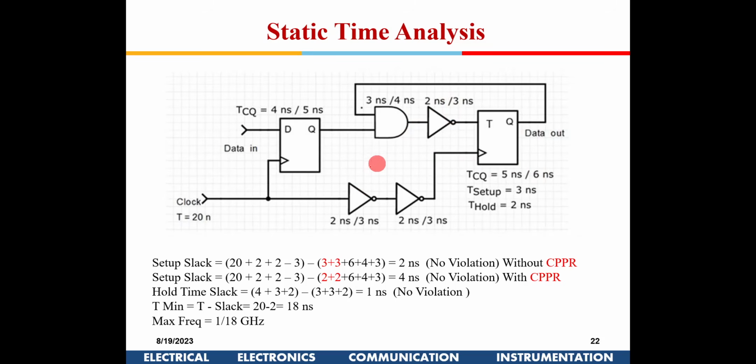Right. So you have to consider the worst case scenario for the setup. So this is the worst case scenario. Now in this worst case scenario calculation, we assume that the next clock for these two blocks, in the first we took as 2, whereas for the data we took it as 3, right? So that is why we have added some pessimism there. Now to reduce that pessimism, we take it as 2 and 2 here. Is this okay with all of you?